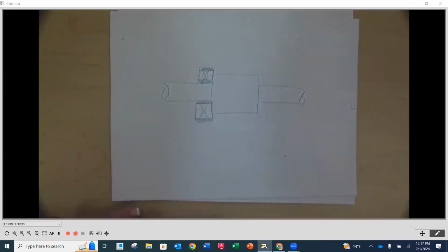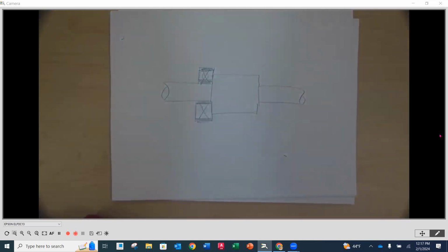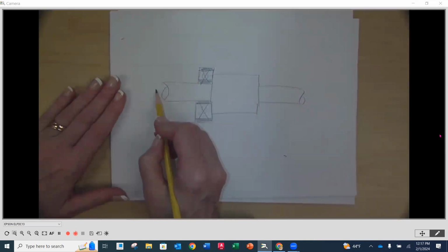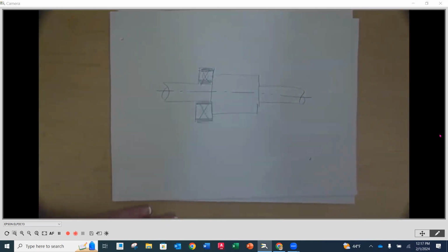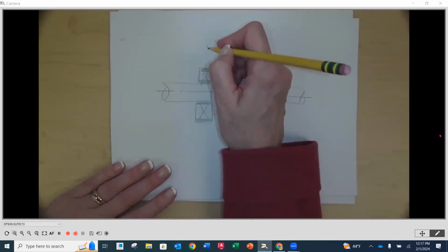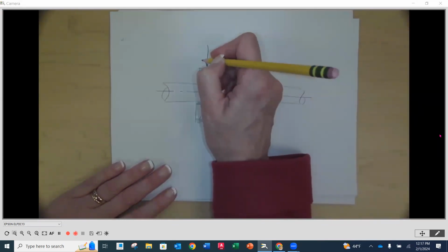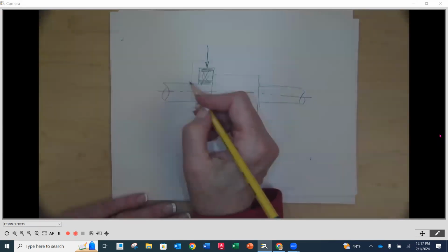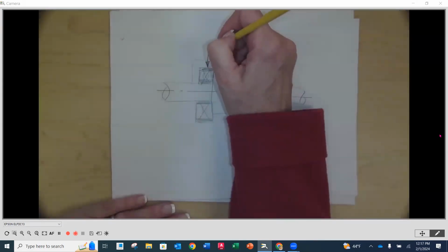So as we look here and talk about radial and thrust loads, a radial load, as I said in the description there, which I don't think is a great description without seeing a picture, is going to be looking at this point, and the load that it's supporting is going to be perpendicular to the axis, or to that shaft. Okay, that's a radial load.